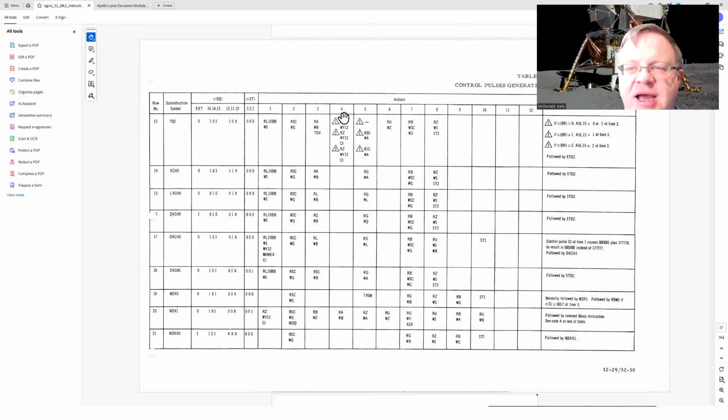For example, in time pulse 4, you can see here we've got 1 if BR, CBR. So in order to do conditional branching, the AGC implements basically two registers, BR0 and BR1. So basically 2 bits of data to give you a branch code. Then depending on the contents of that branch code, we can say, okay, if it's 0, in this case, we would do an RZ and then a WY12. And we'll go through these in more detail as we look at each register.